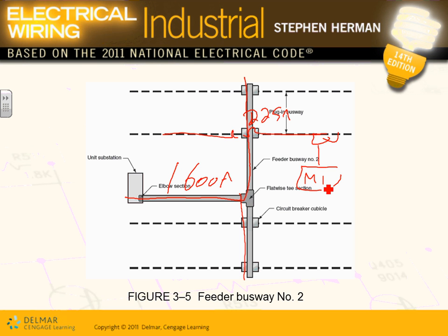What's important for you, Karen, for your project, not next week, the week after, when we start laying out power, is that it's going to be exactly this way. You're going to bring a feeder busway from the switchgear into the manufacturing floor, cap that feeder busway with 225 amp plug-in busways, and then from these plug-in busways, you're going to put a few switches with an SO cord, and you tap into all these machines that we have in the manufacturing floor.